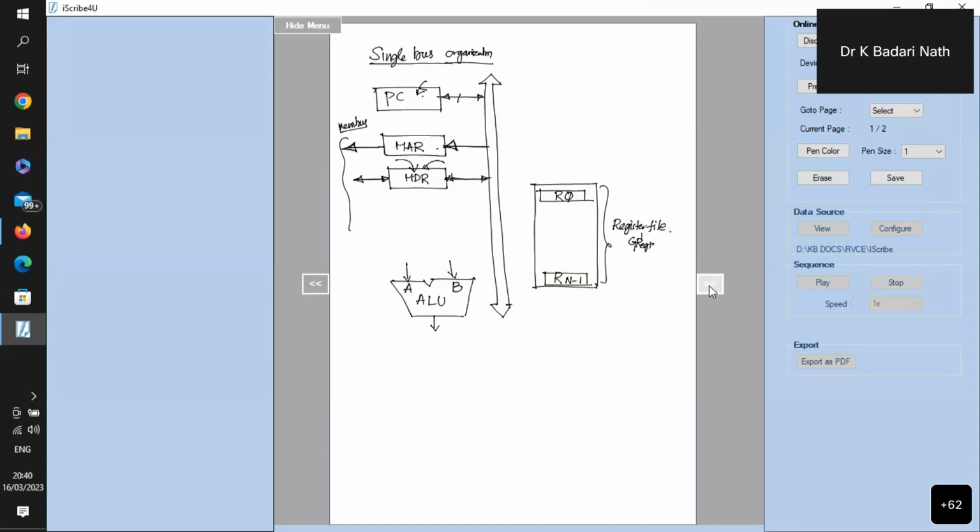General purpose registers means these registers are available to the programmer either to keep data, to keep a pointer, or for temporary storage. It is left to the programmer to declare the variables and allocate registers to them. The way the programmer thinks, he can use all these registers. Now, the processor also provides one register, called the instruction register, which holds the instruction as soon as you bring it into the processor.